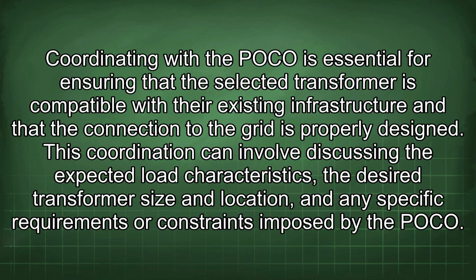Coordinating with the POCO is essential for ensuring that the selected transformer is compatible with their existing infrastructure and that the connection to the grid is properly designed. This coordination can involve discussing the expected load characteristics, the desired transformer size and location, and any specific requirements or constraints imposed by the POCO.